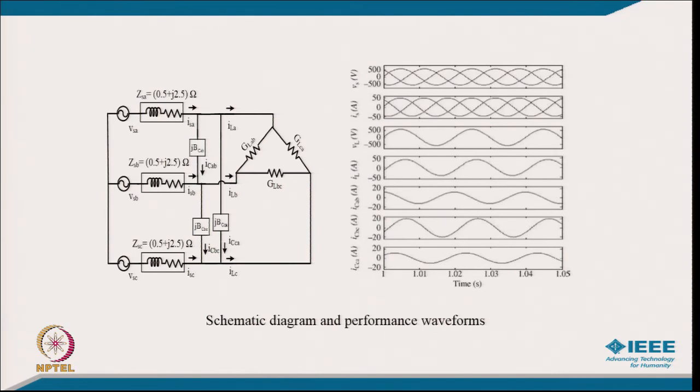Well, this is typically again a network. We have a balanced source impedance, which is responsible for reducing the voltage, but we have to regulate it to zero voltage regulation. We have an unbalanced load, and by putting in the compensator elements we should be able to balance the load and then regulate the voltage. So we have to find the compensator element values in susceptances, which are lossless elements.